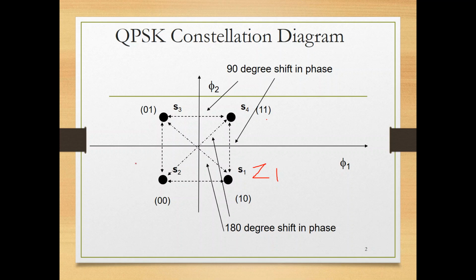Basically, to implement the QPSK modulation, you need to follow a mapping table to establish a rule. This rule maps the bits into symbols, and in QPSK these symbols represent the phases. All the symbols have the same amplitude and the same frequency. The only difference is the phase. Phase determines where each symbol is located, in which quadrant or in which zone.